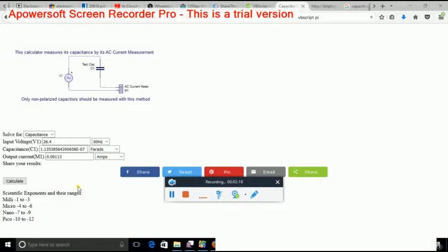And another thing is, if you measure a big capacitor, like 100 microfarads or so, it can probably draw a lot of current. I tested a 45 microfarad bi-motor capacitor, and it came out to be like 444 milliamps. That seemed kind of high. Not very high though, but it could be if you use the wrong kind of transformer.